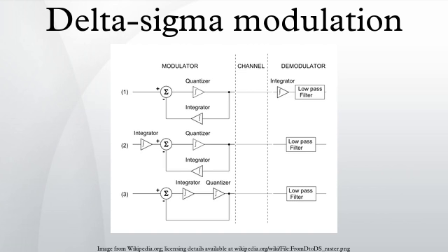E, the comparator output. The comparator is a very high-gain amplifier with its plus input terminal connected for reference to 0.0 V. Whenever the negative input terminal is taken negative with respect to the positive terminal of the amplifier, the output saturates positive, and conversely negative saturation for positive input. Thus the output saturates positive whenever the integral goes below the 0 V reference level and remains there until it goes positive with respect to the reference level.